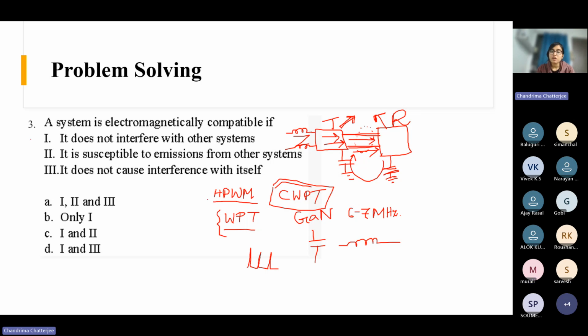Obviously. When I work on power electronic circuits, sometimes what happens is, suppose I am running my setup, and somebody else adjacent to my table is also running her setup, and she just turns on some voltage source or some emulator, then my system gets disrupted. That is a clear sign of EMI. The moment she turns it on, my waveforms get distorted.